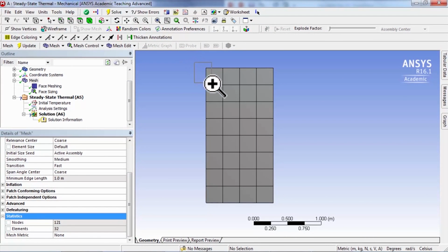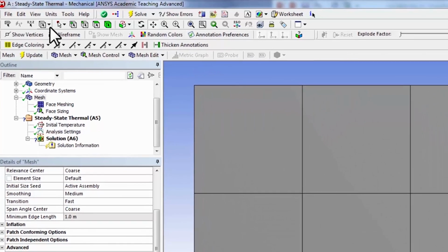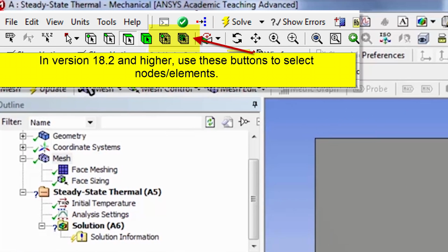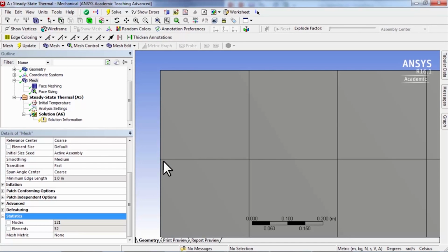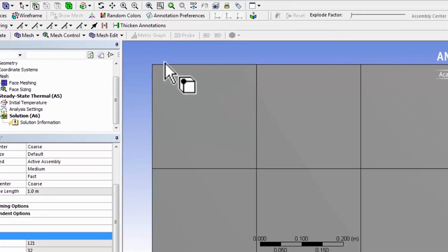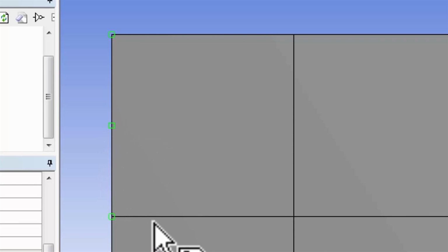Let me zoom in here using the right mouse button, and let me translate it. And I'll go here and I'll say select mesh. And then make sure that the vertex option is on, so I can select elements, which will select this, or I can select the nodes using this option, and then I will just drag it over these locations.